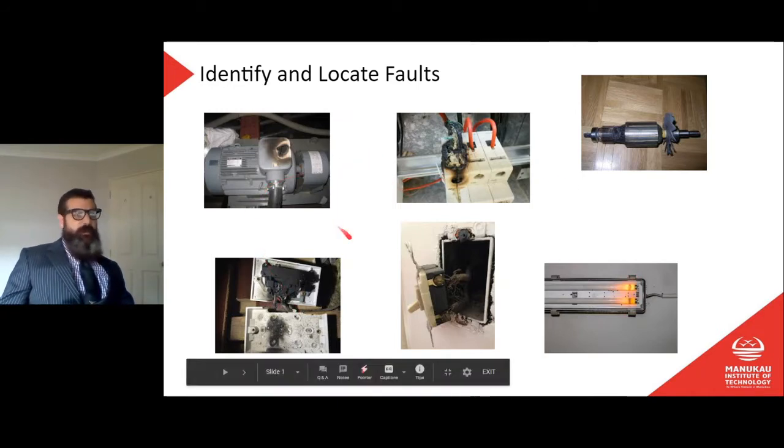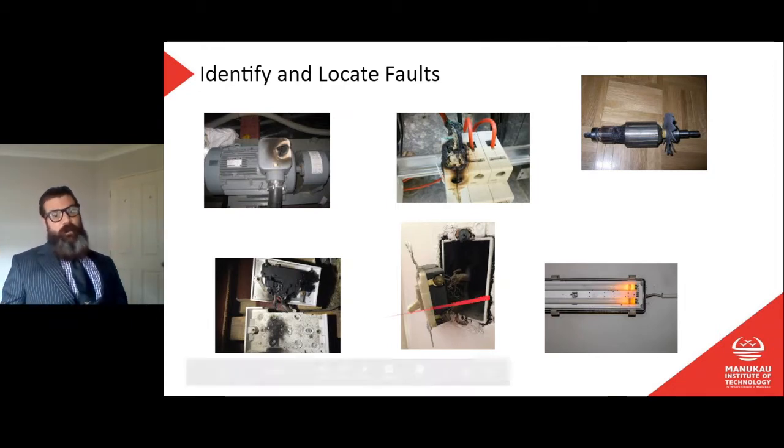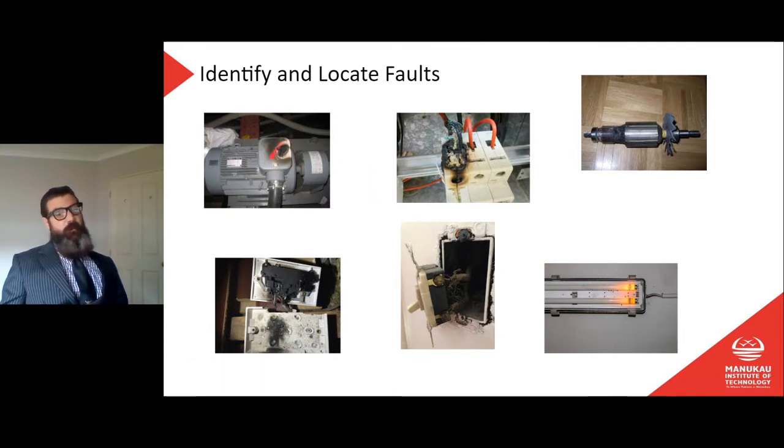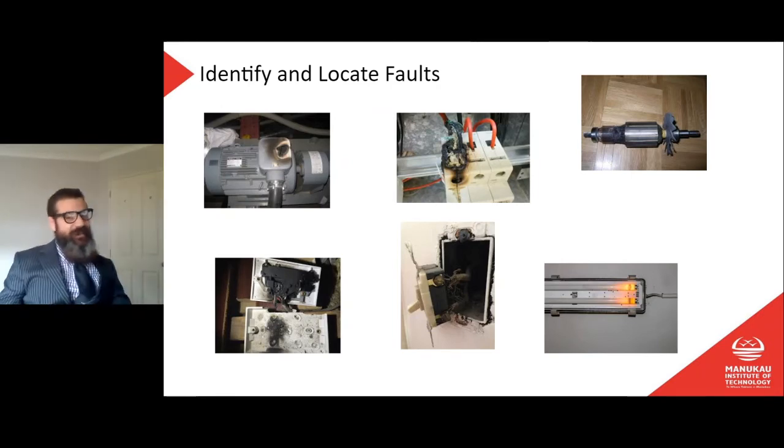What does this tell us? Right from the get-go, this tells us that your first and most important tool for fault finding is your eyes. Go and have a look around, because if you walk in somewhere and someone says, well, the motor doesn't work, I push the start button and nothing happens, and you see a big burn mark on the top, and you go and look somewhere else, straight away you've screwed that up. I don't need to tell you that, right?